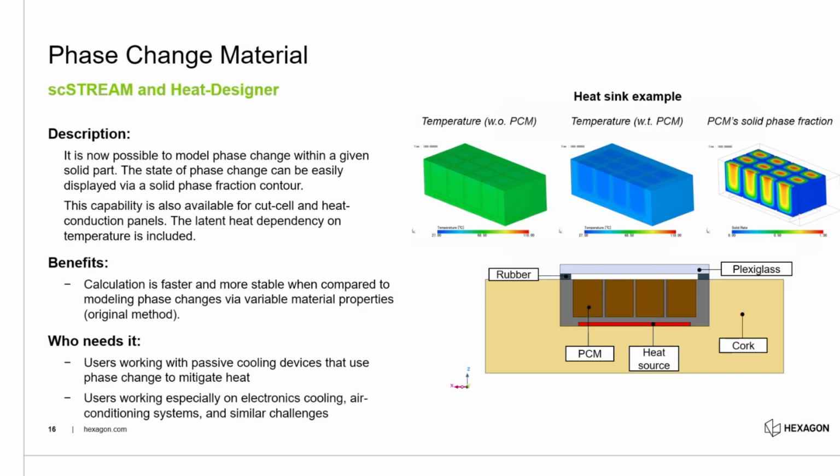Another interesting material is phase change materials. So we're used to thinking of phase change as something like water going from ice to liquid or liquid to gas. And the amount of energy that you need to change that phase is really significant. So let's say you have ice at -2 degrees Celsius, you heat it up, it goes warmer and warmer until it starts to melt. And then while it's melting, the temperature doesn't really change. So it kind of fixes it there for a while.